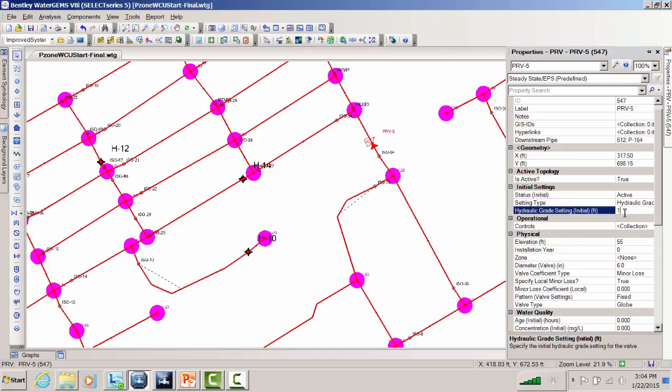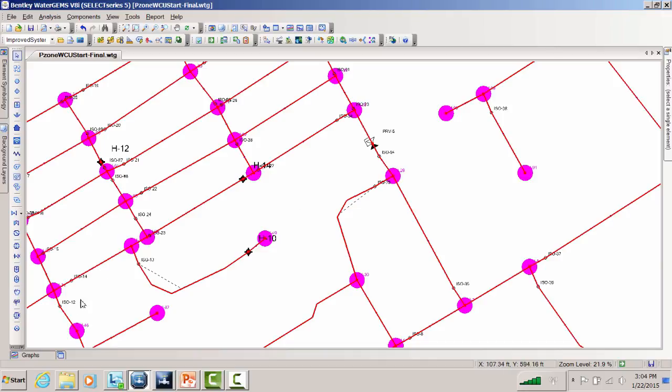At that time, this sleeper PRV is going to wake up and start feeding into the zone. So if you're doing some maintenance along that line by the meter, or whether there's excessive flow due to a fire, this thing will open automatically. So this now defines a pressure zone.